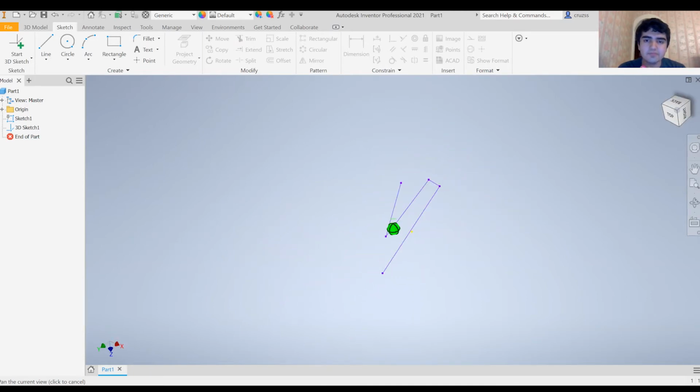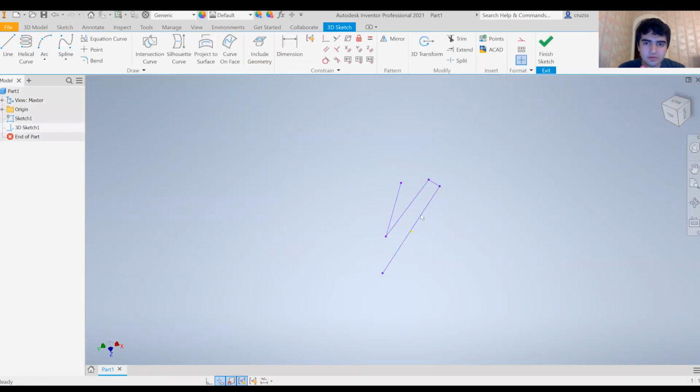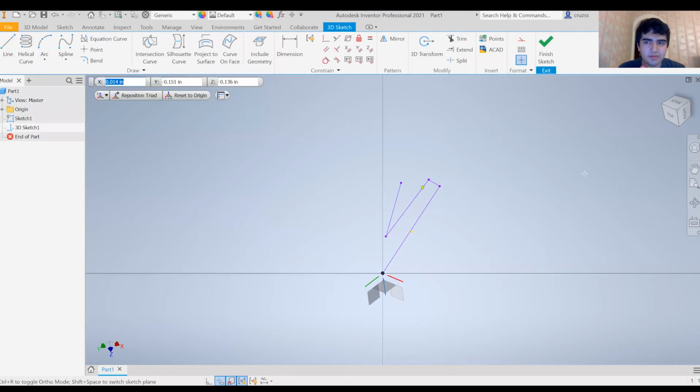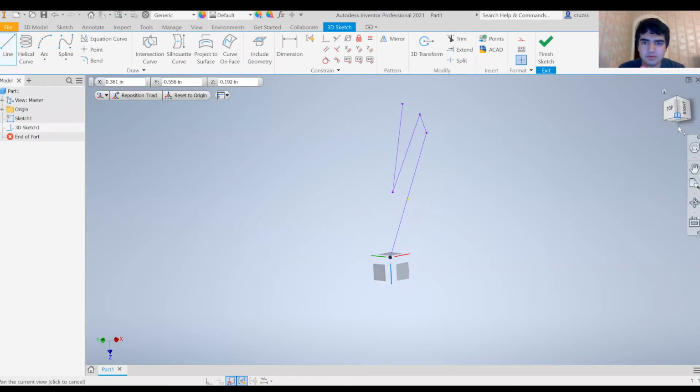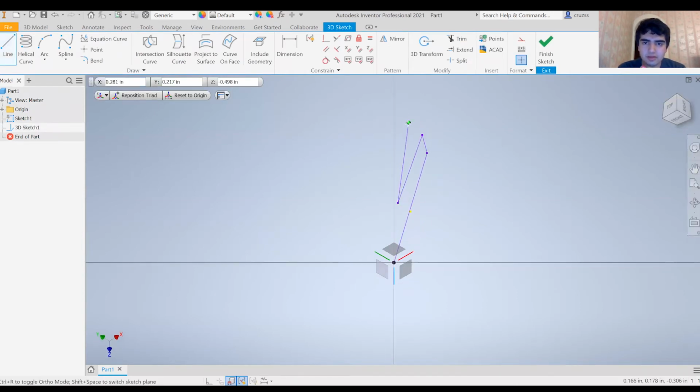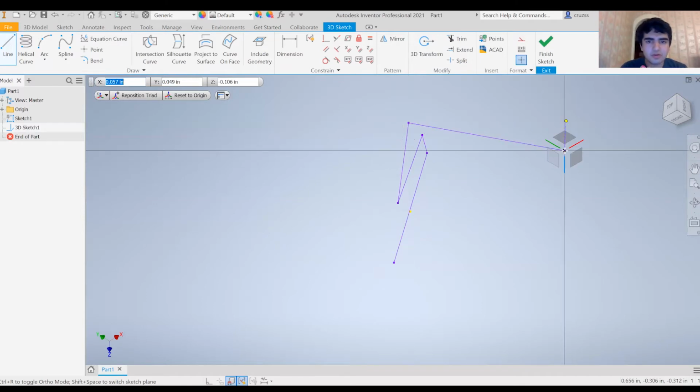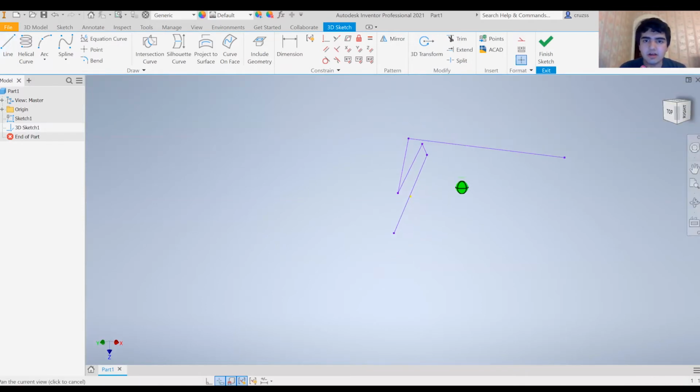As a matter of fact, if I went back into this 3D sketch, I opened it again, create a new line. So right here, create a new line. As you can probably expect, this line is now going off in a completely different direction. This is the plane originally that we had made right here. All of these lines that we created went in this one direction, but now this line is going a completely different direction. It's offset from those lines.